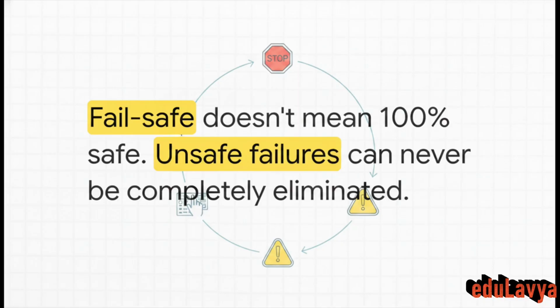When a highly sensitive SIL 4 system safely shuts down trains due to a minor equipment fault, the signalers and operators are forced to use manual, degraded mode procedures to get trains moving again. And the second you revert to manual procedures, you bypass your computer safety nets and introduce the massive risk of human error right back into the equation. A system that cries wolf and shuts down too often actually becomes less safe overall because of the human interventions required to fix it.